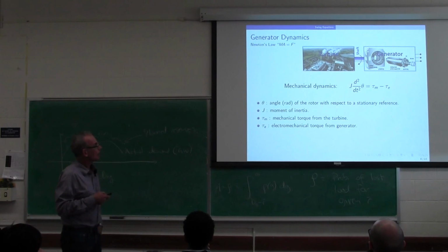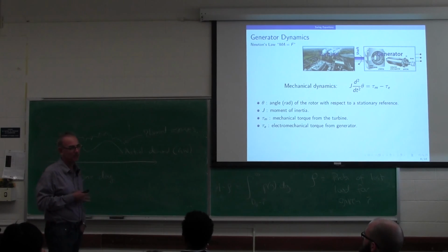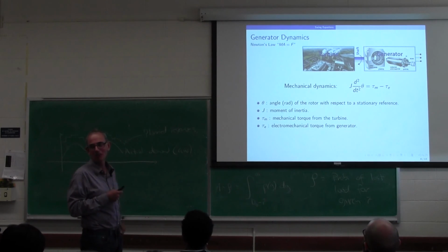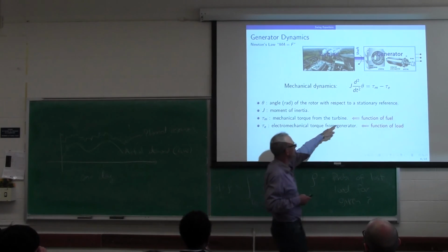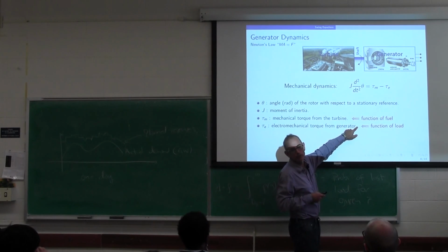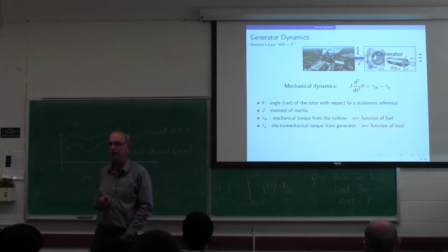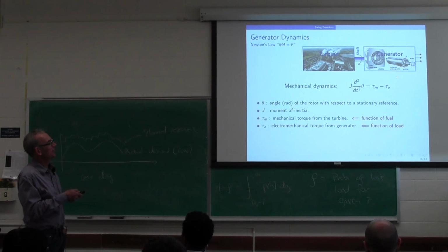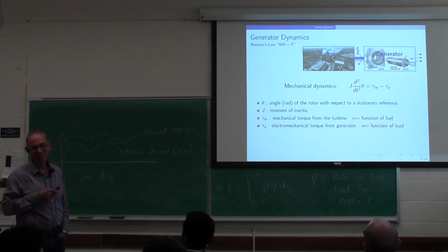Now, that's not really what we want. Most of us aren't mechanical engineers. We don't care about torque. We care about power in all its forms. And so, I should say again, this is a function of fuel, and this will depend on load. The torque will disappear if there's no load, which is scary. So if the load suddenly disappears, wham, this thing's going to accelerate and trip. You're going to have a problem.